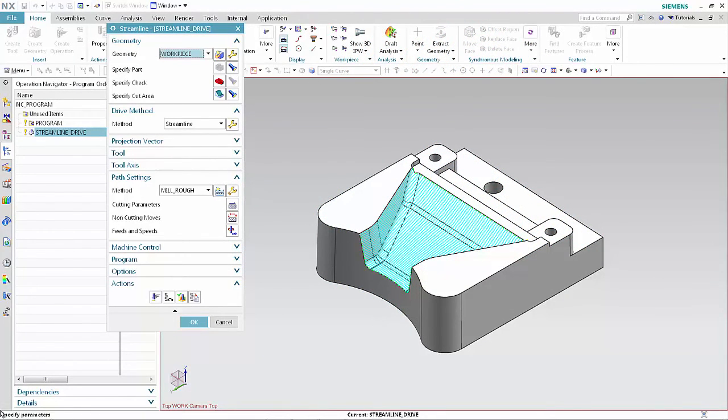The curves are saved in a named group in the Part Navigator and added as sets in the flow curve and cross curve lists. As geometry in the part, you can trim, extend, bridge, or remove the curves individually to improve your toolpath in areas that are difficult to machine. These curves, however, are not associative when saved as geometry in the part. If the cut area geometry is modified, the saved flow and cross curves do not automatically update.